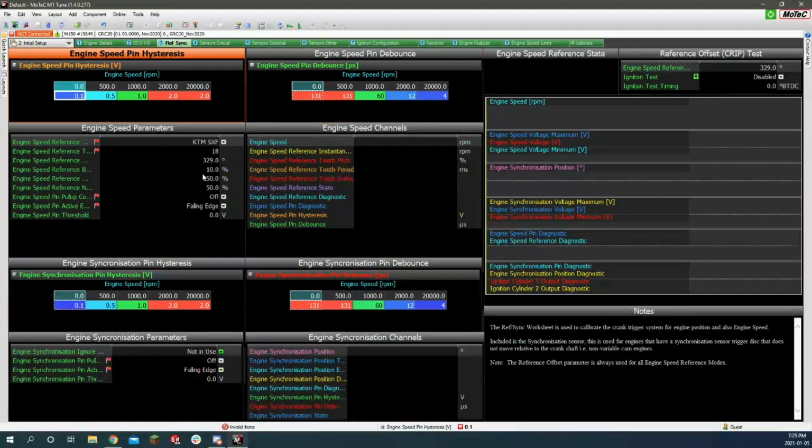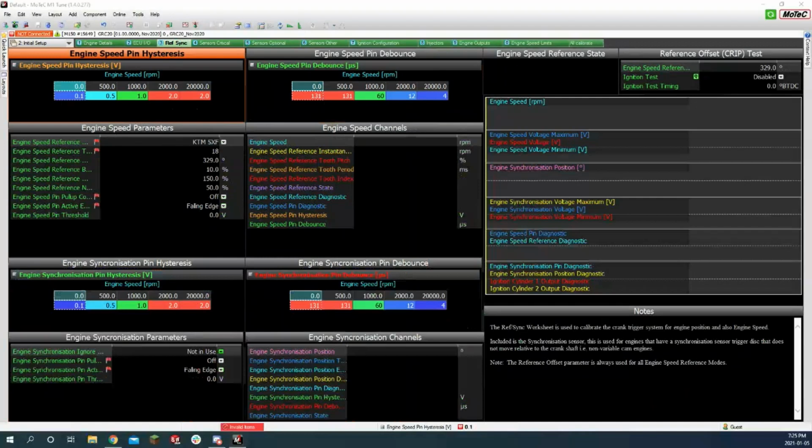This page is kind of boring. It's just some history, just stuff and sensor things. So, the crank sensor on the engine. That's the sensor that reads the reluctor wheel on the crankshaft of the engine, and the sensor is able to pick up how fast the engine is spinning and where the engine is angularly. So it knows what stroke the engine's on.